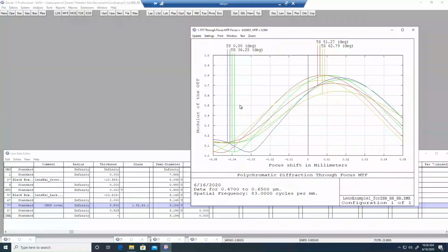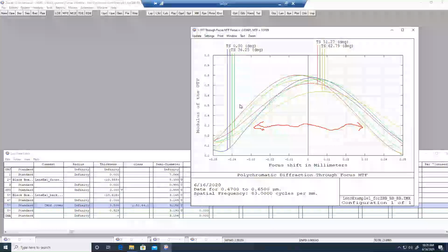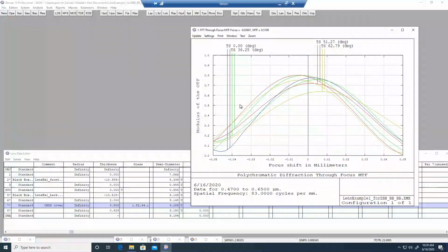Okay. So basically, the space underneath the curve, right? How much that is opening up gives you, whatever your minimum MTF you can accept, right, that space when one field curve or the other ones are touching, that kind of gives you the amount the lens could actually shift due to temperature, or what you just mentioned before, maybe due to process tolerancing or something, right? Yes, exactly.